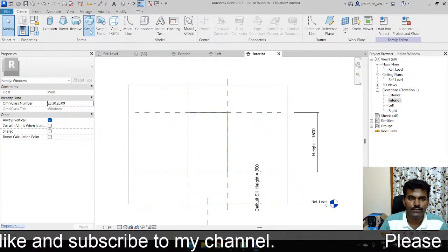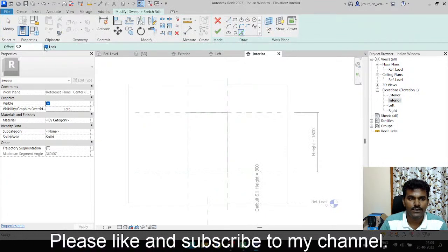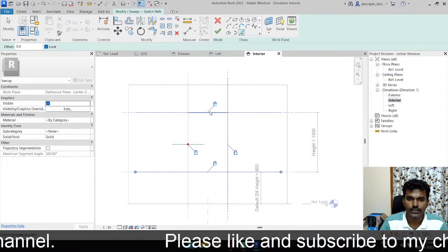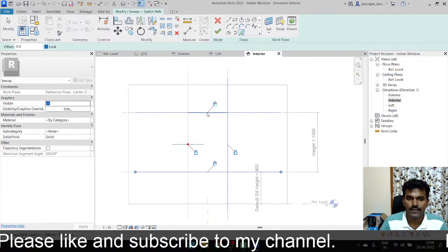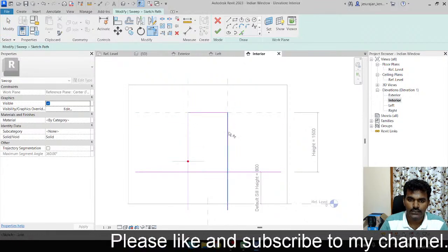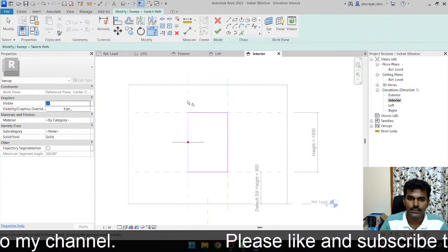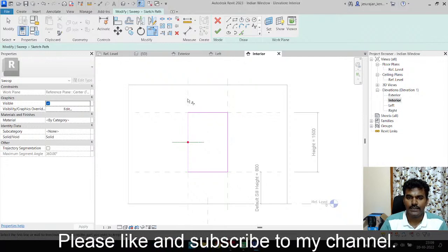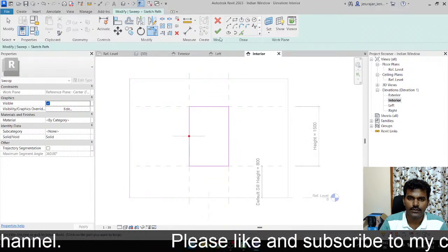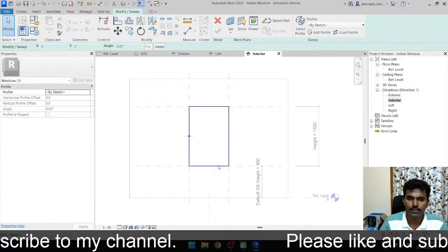Now I can take a sweep, go to sketch path, pick a plane and keep that as locked, select the reference plane. You can see whenever I'm clicking the line, the sketch line automatically gets locked with that line. That's an easy part, right? Now I have fixed the boundary of the window. Boundary, whatever you say, it's just referring from the reference plane. So this is my path, the sweep path.